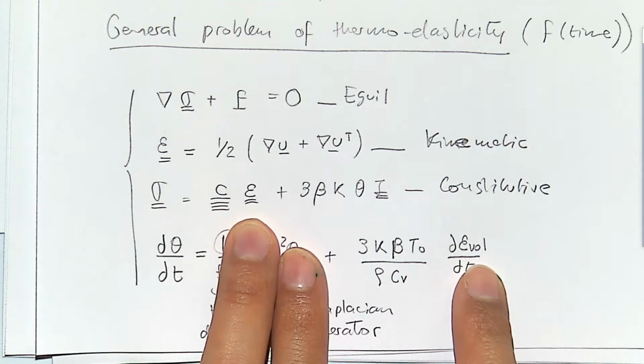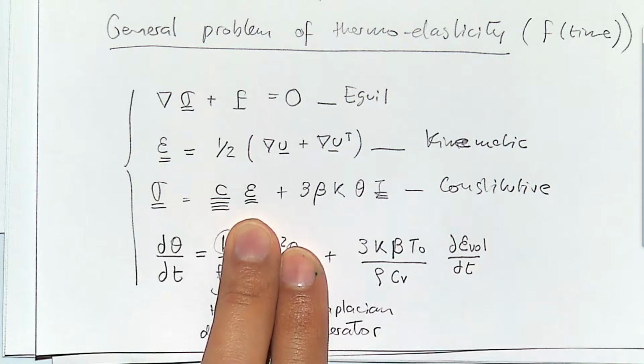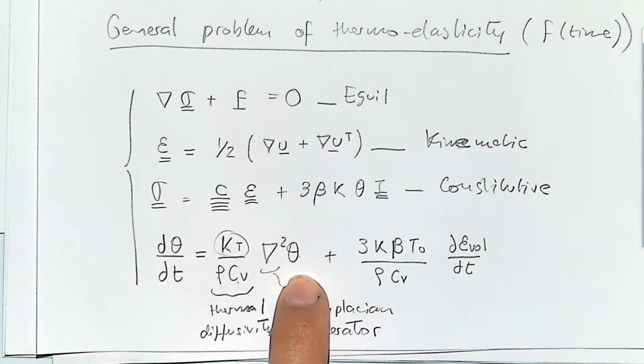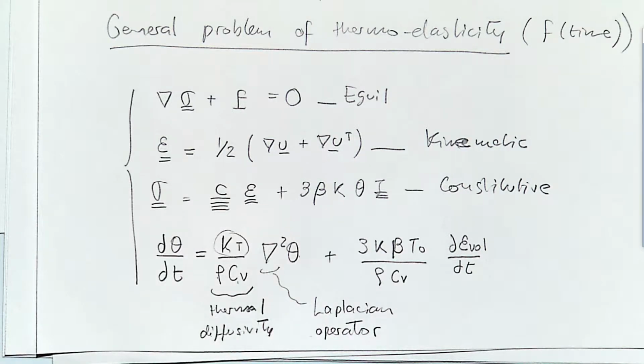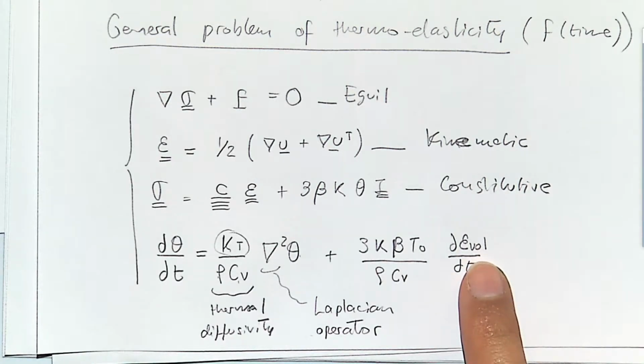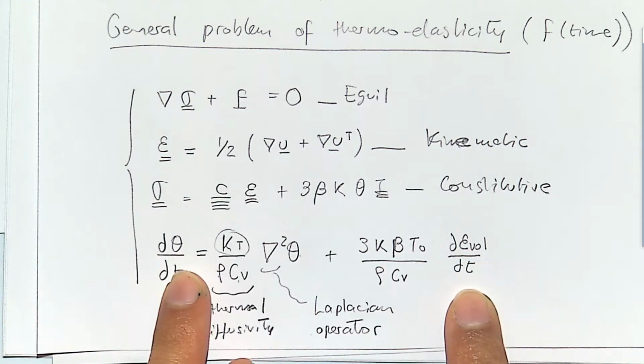When you deform a solid, it takes energy as strain energy, but also in the form of heat. If you have a piece of metal and you bend it back and forth, eventually it's going to heat up and it might break. And this is that component over here. A change in volumetric strain can lead to a change in temperature.